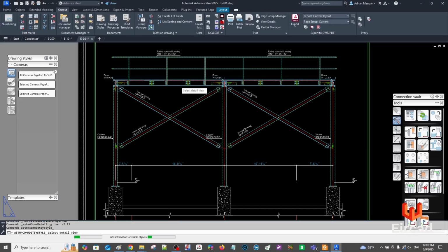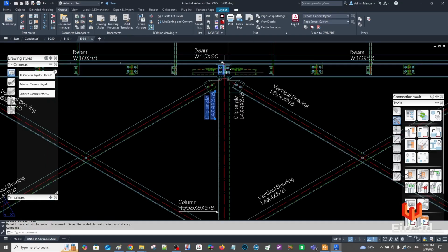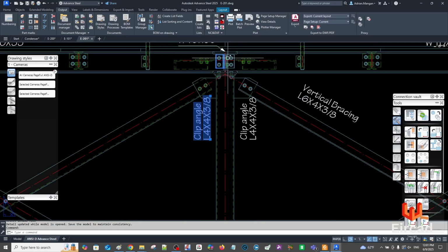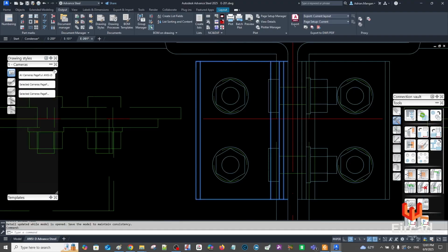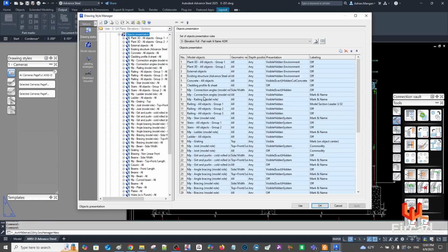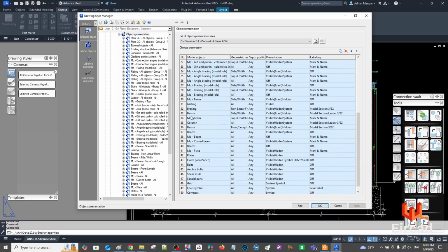There's a little bit of tricking around in it, and I kind of do it on a daily basis, but sometimes it's hard to find some things. So you can see it's coming in for the clip angles, right? I don't want the clip angles on that, obviously. Also those clip angles are coming in as exact. We don't want them as exact. So generally what I'll do with that is I'll just create one for clip angles, right? Sometimes there is one already, but it's probably for the main parts.